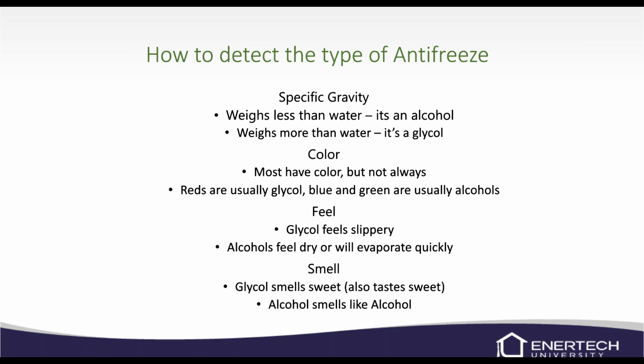A lot of times I can base it off of how it feels. A glycol will feel really slippery. When you get it on your finger, it'll feel real slick. Also, as it dries, your finger will be a little bit sticky because of the sugars in it, so it'll be kind of tacky. Alcohol, when you put your finger in it, will have almost a cooling effect when you pull it out because it starts to evaporate. It'll feel kind of dry and cool your finger off.